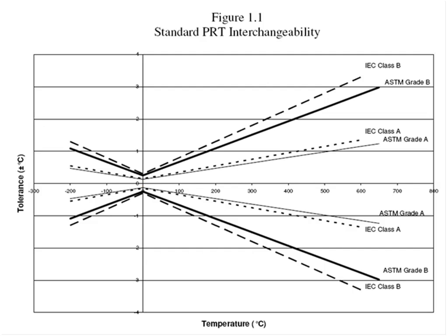One would be, when you're speccing out an RTD, to make sure that the interchangeability was measured at the end of the lead wires, because in some cases, if you have a 3-wire circuit on an RTD, that cable can introduce some error into that measurement, and if you have a long cable, it can be more of an issue. Shorter cables, or just maybe 3 or 4 inch long lead wires, typically not too much of an issue, but just the fact that it's measured at the end of those leads in the completed sensor really is important to know.